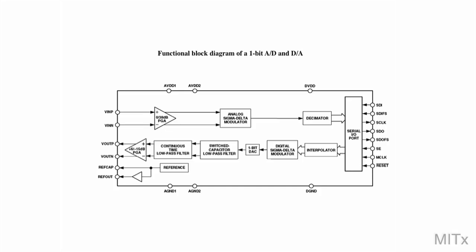Typical A to D conversion now involves what's called sigma delta modulation, and I'll be saying something about that in Tuesday's lecture. It involves a very high degree of oversampling on the analog signal, followed by some processing and then decimation, in other words, downsampling. And then in the D to A conversion process, there's exactly the reverse, which is to take the one-bit digital data, interpolate it, and then come out through a one-bit D to A converter to the output.